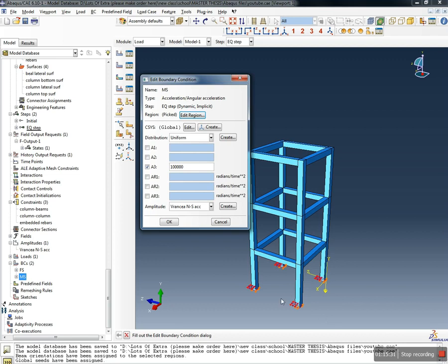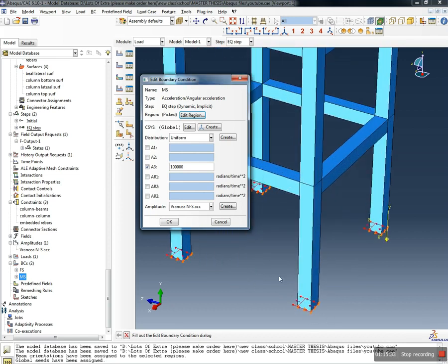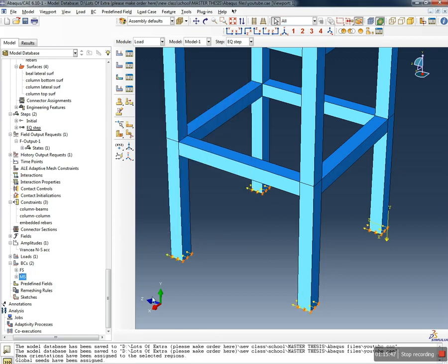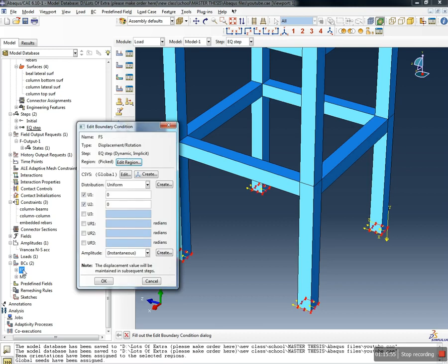Yes, we do. Or do we? Yes, we do, because otherwise we would have got some warning that the region does not exist anymore. I was a bit worried that since we suppress and resume again, it might not work. But it works. So if you define boundary conditions and then suppress the regions where you defined them, and then resume them again, your boundary conditions will be fine, which I'm sure is not valid for mesh.